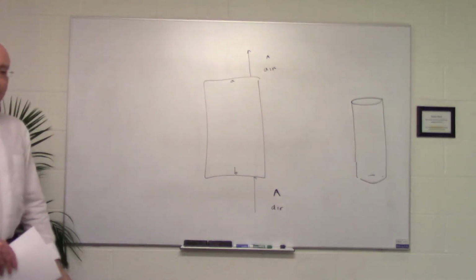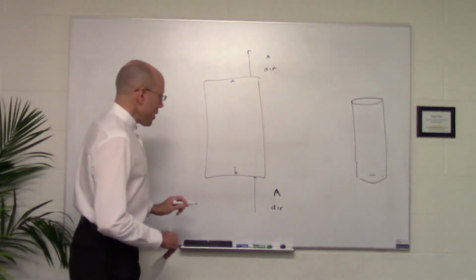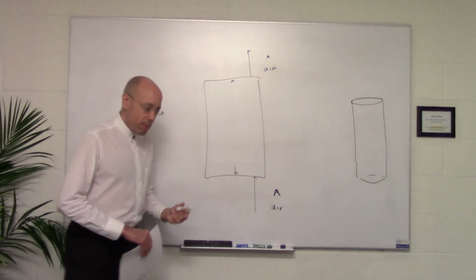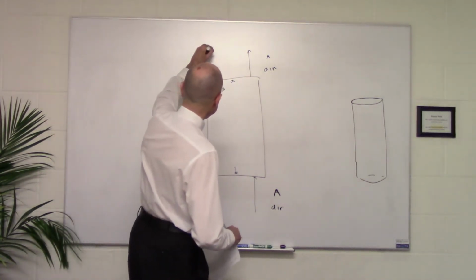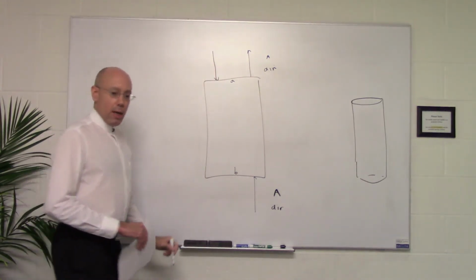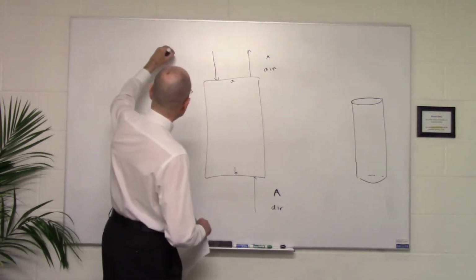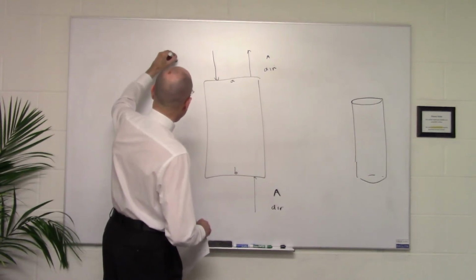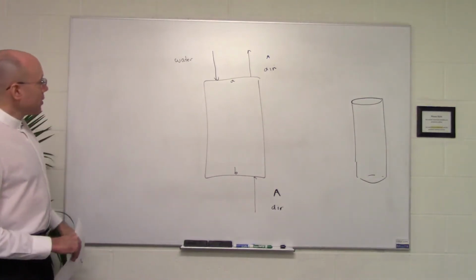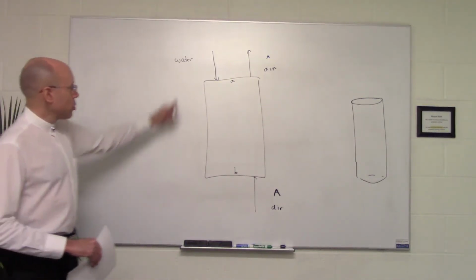So we'd like to get the A out of the air, and the way that's often done is with gas absorption or gas scrubbing, which is contact with a liquid. If we're talking about ammonia, a good way to remove ammonia from air is to contact it with water. So there's water coming in. And let's say the water comes in clean, so there's no ammonia here.